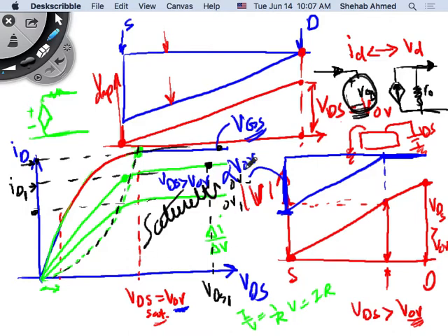Why do you want to operate in the saturation zone? Because in the saturation zone, you have a value of current that is not controlled by the voltage across the device. It's actually controlled by your control signal, the gate voltage, which is nice. Right? At the gate, you're not drawing any current. It's like if you have a sensor. You put your sensor there, and you're not going to draw current from the sensor. I will just measure the voltage across the sensor. I will trickle current. The capacitor charges using that current, and that's it. It maintains the voltage. So I will put my sensor across that input capacitor, for example. It will charge the capacitor to a certain voltage, and that's it.